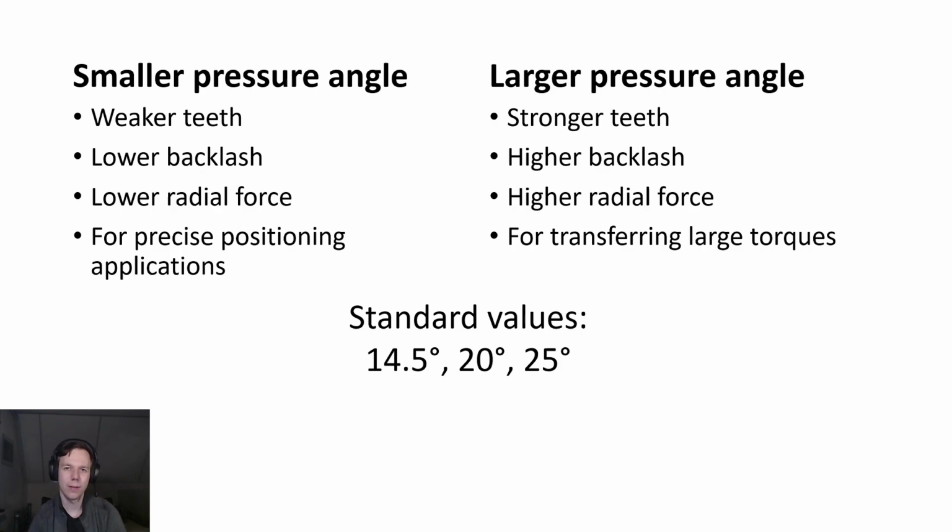The next thing to think about is that if you have a higher pressure angle, the radial forces acting on the gear train will also be higher. And this too requires a little bit more explanation, but this time we'll go to the whiteboard instead.